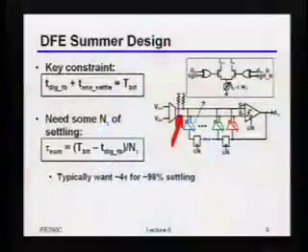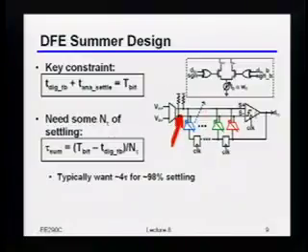Now, by the way, not only do I have to get that sort of 8 or 9 gigahertz from just a standard amplifier, but remember, there's all these extra current steering switches sitting there, right? Each one of those things has some cap that it's going to be adding to your output. So that means it's going to be even harder to actually get that speed constraint, okay?